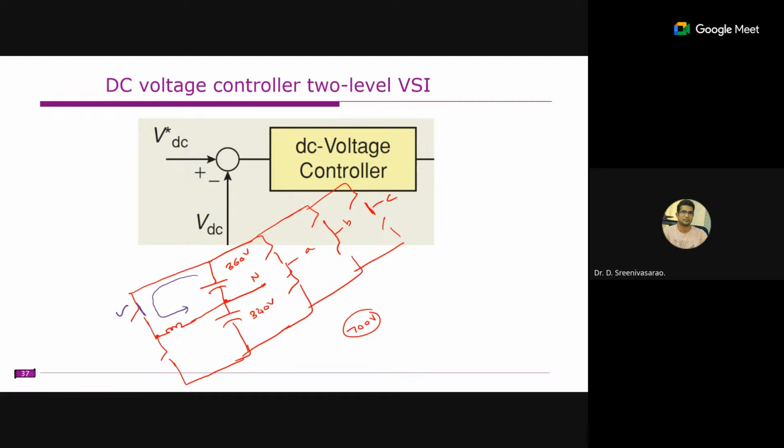the inductor. So how long do we need to store? This capacitor will be discharging, slowly its voltage will be reduced. So once this voltage is changed to 350 volts, now we will open this switch, right? So we'll discharge this capacitor and we will energize this inductor, or transfer this energy to the inductor.